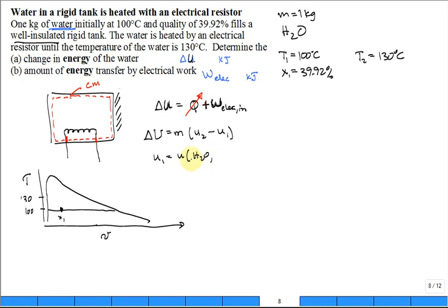It's water. Don't forget it's water. Sometimes people say, oh, it's water, let me go to the refrigerant 22 table or whatever, right? Let me use PV equals RT because I used it before, the previous problem, ideal gas equation, right? Don't use that for water, especially in the dome. Believe me, I've graded enough exams. Students forget what substance they're working with, and they run off and grab whatever table and whatever equations. So it's for water. Use the steam table, and we have to fix the state.